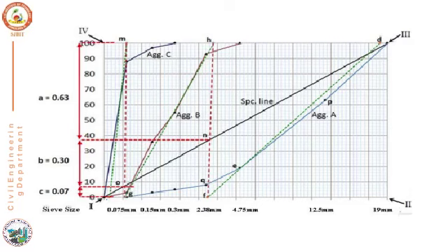draw the aggregate gradation line. First step, what we have to do is draw an x-axis of about 15 centimeter and take 10 centimeter for the y-axis. Mark percentage passing on the y-axis, that will be the first step. Once it is ready, draw an inclined line from 0% pass of the smallest size to the 100% pass of the largest size. Draw an inclined line of suitable slope which will represent the specification line or desired gradation line.